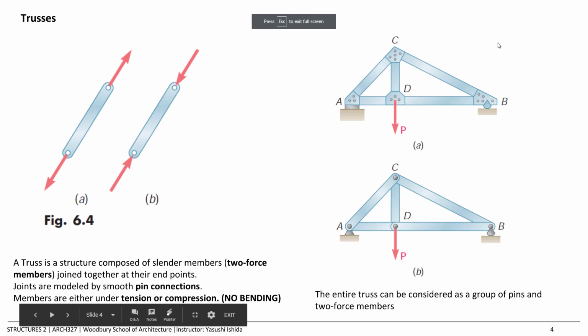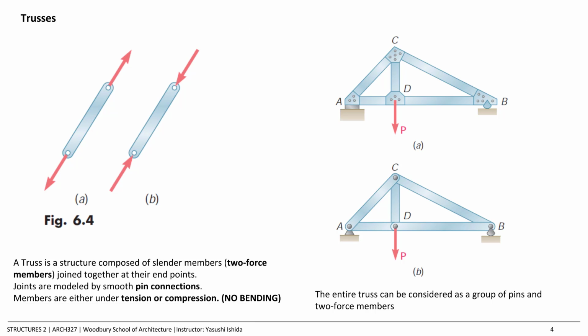All right, so we're going to talk about truss, which we kind of did last week, but in a more comprehensive term. A beam resists the load by bending, but truss is only through axial force. What does that mean? Let's read that because I wrote it in.